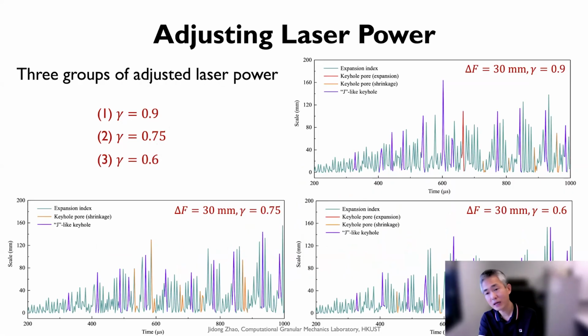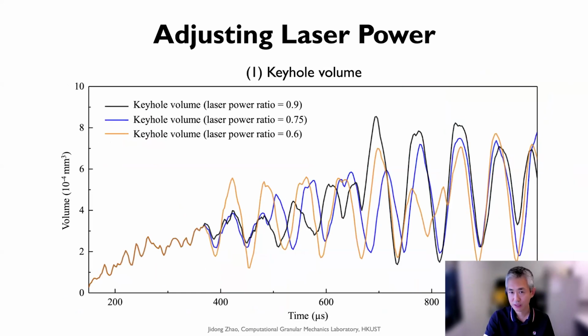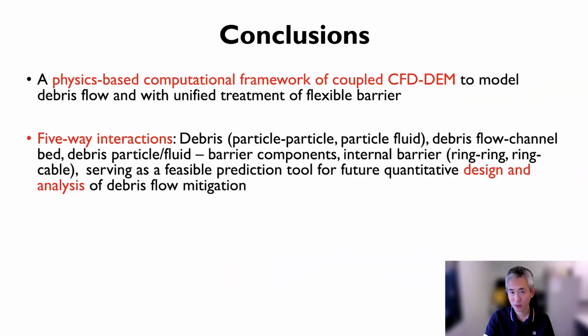So this is how, based on our high fidelity simulation, we understand the mechanisms, and then we identify different formation stages, and then we adaptively adjust the laser power for optimal printing here. Okay, again, these are the printing results here.